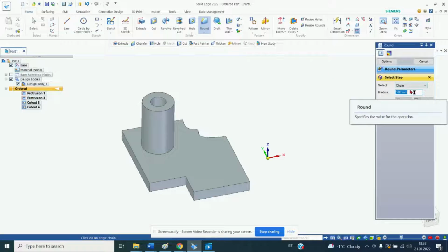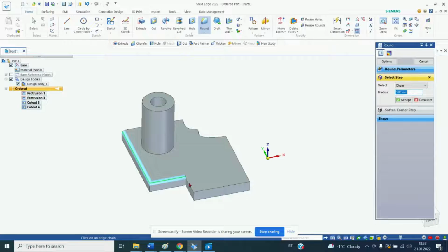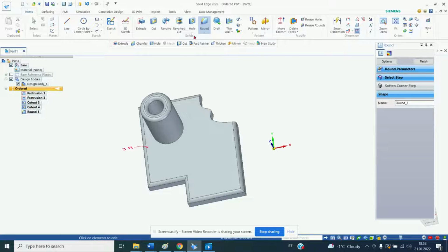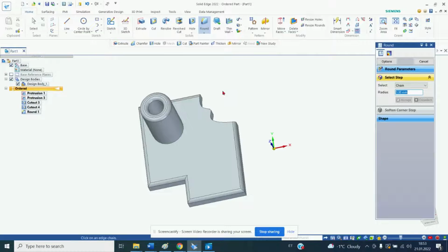There might be an error message in the Curve cutout when Solid Edge cannot make the radius there. Make other radiuses and try to make it again or change the radius to a smaller value. Tip: if you are modeling a part for 3D printing, try to avoid parts and edges smaller than 1 or 2 mm. Most 3D printers cannot make such small differences.